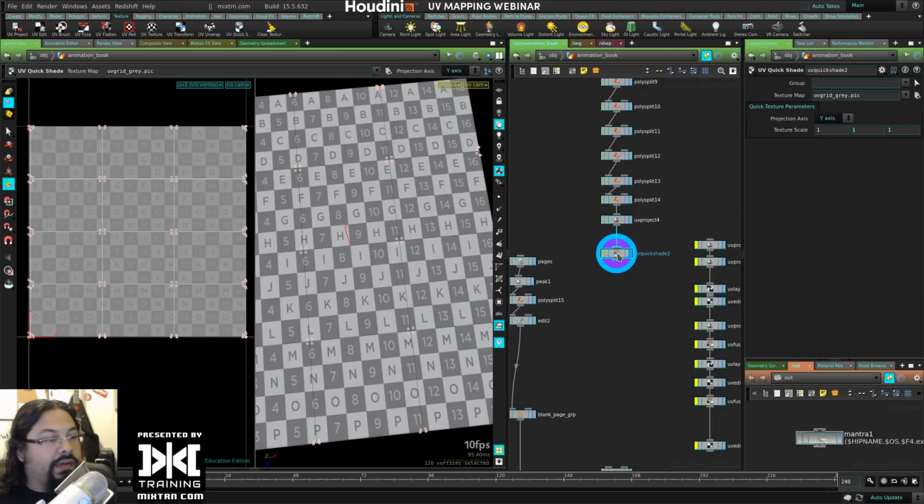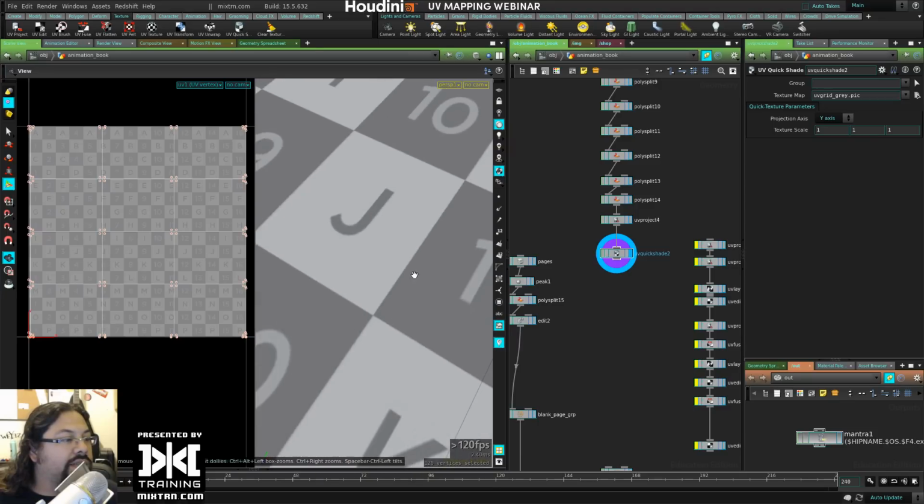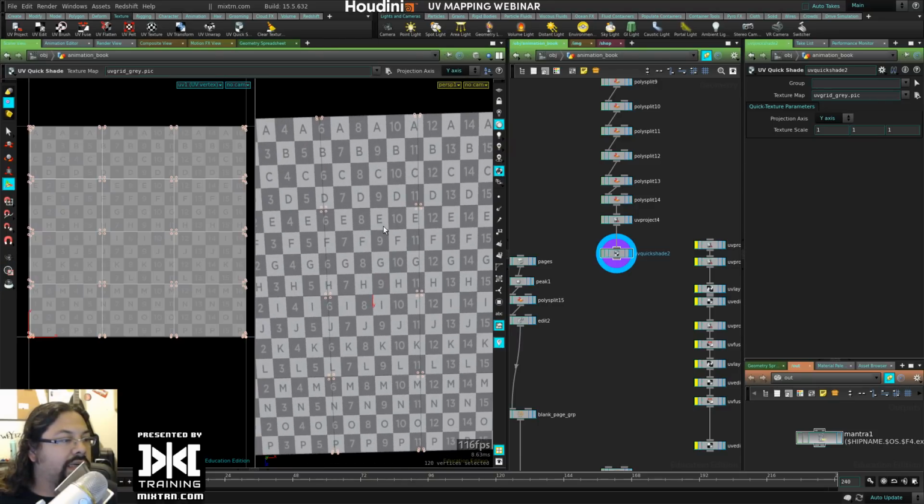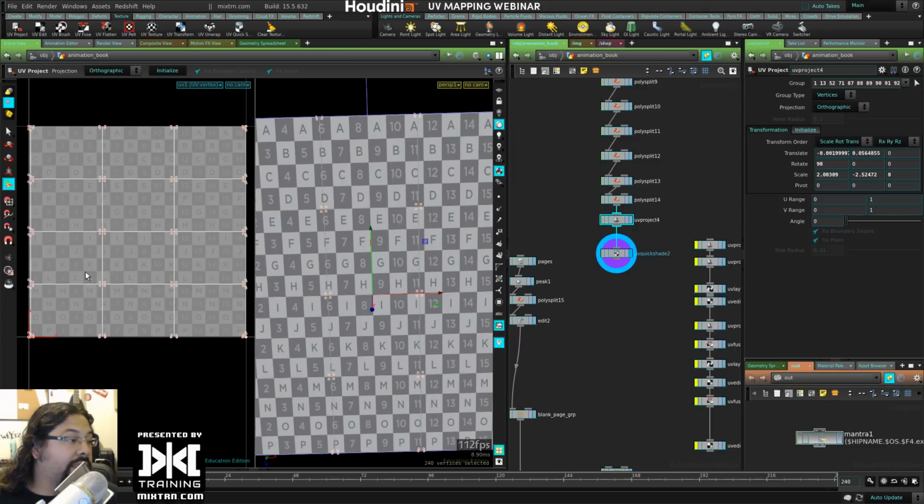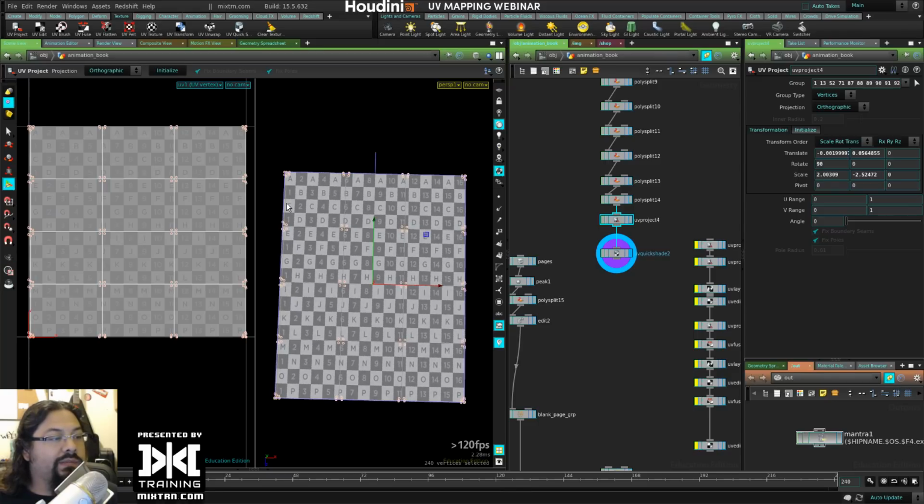Sometimes. All right, but another thing you can see here is that these UVs are actually distorted. You can see the squares are not real squares, they're kind of stretched. And using the UV texture, you can't actually get correct proportions. We do want the correct proportion for this patch here, because we're gonna apply a texture that is already at the right size. So we're gonna project a few more times and merge those to make the whole cover.